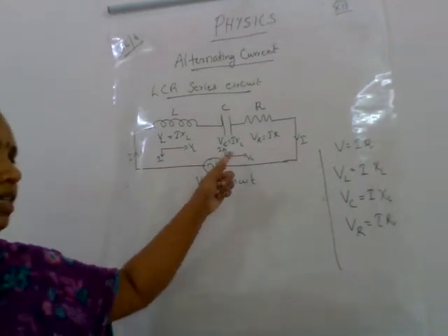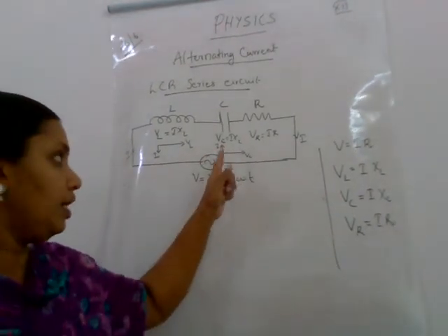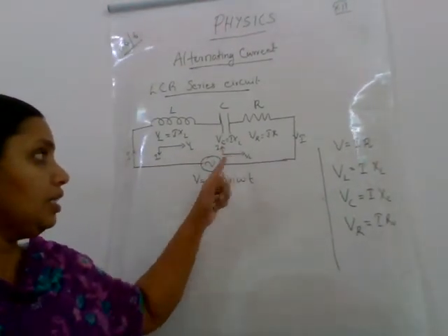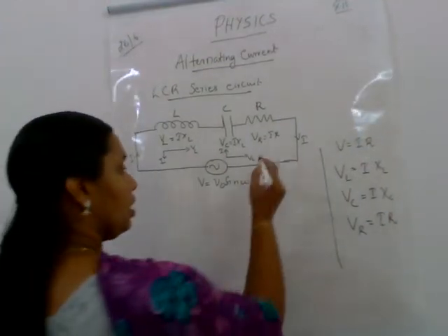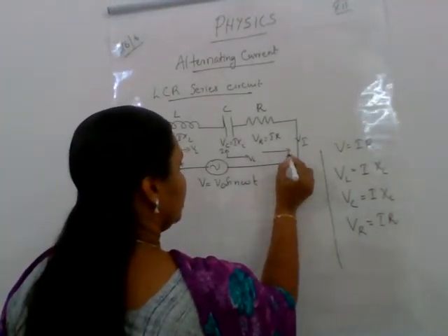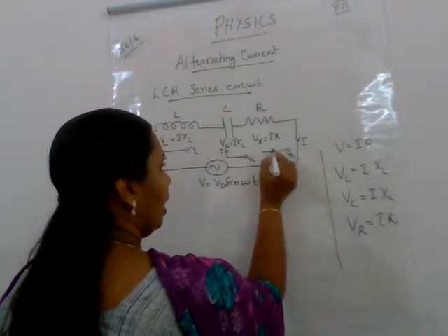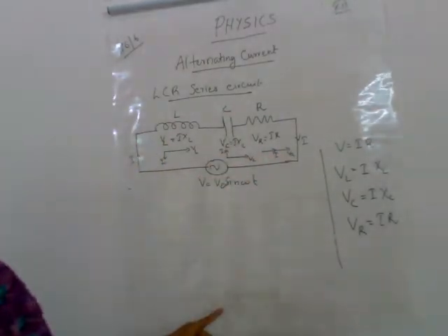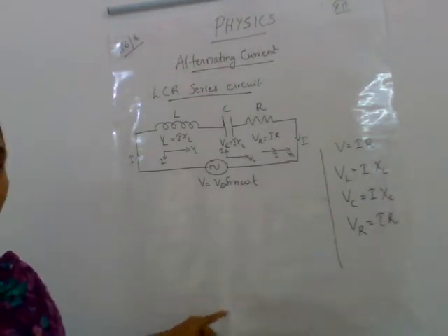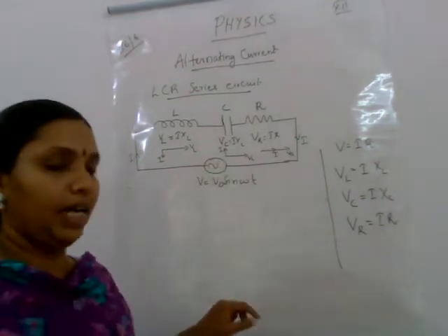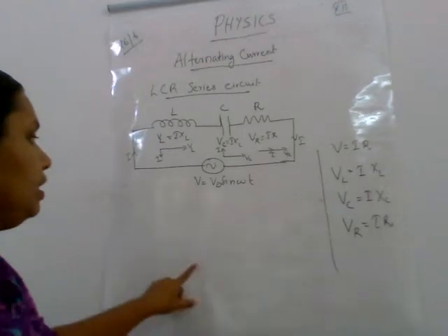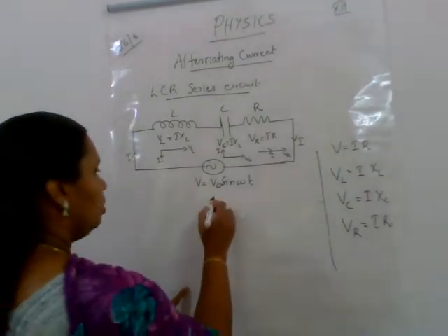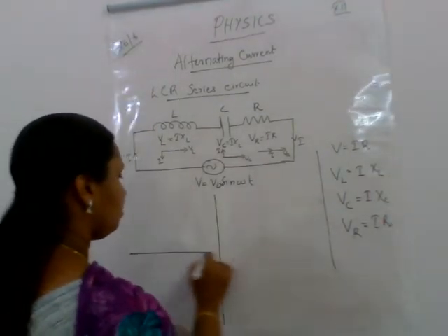This is a phasor moving in the anti-clockwise direction, so here current leads voltage. And in the last case, this is VR, and I will be in the same direction. These are the individual phasor diagrams. Now I am combining them and drawing the phasor diagram.